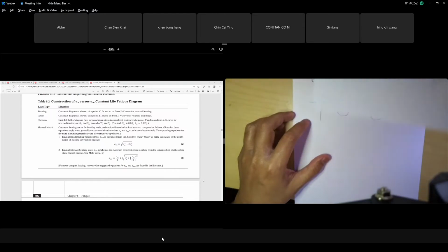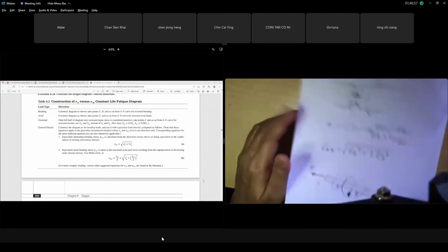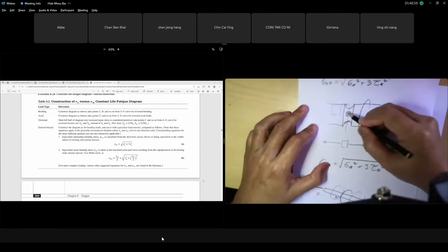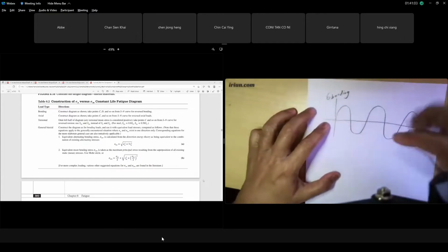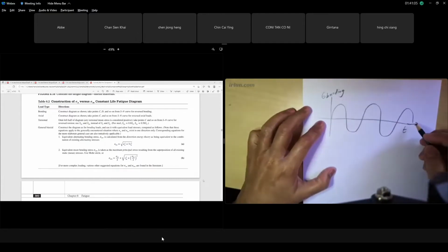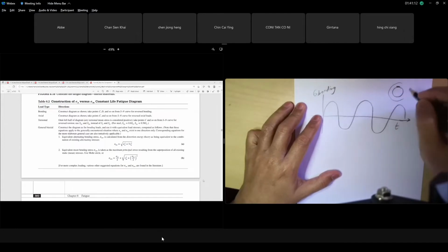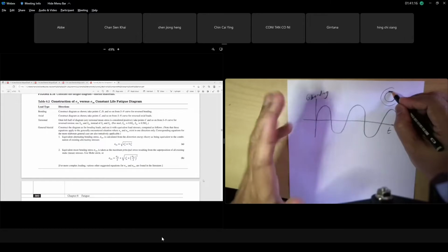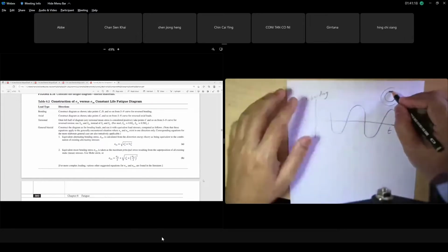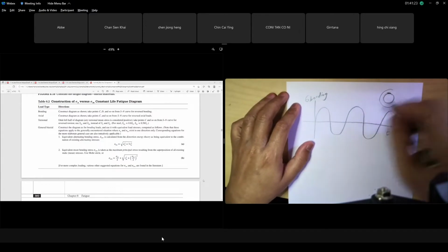Okay, in our case here, for bending stress, the shaft is rotating, so your element will face a plot of sine bending through time. It becomes like a sine wave, completely reversed. Betul tak? Remember I said, if your shaft is rotating, your element at the top and your point of interest at the groove, at the notch, will face tension and compression stress, but it remains the same value.